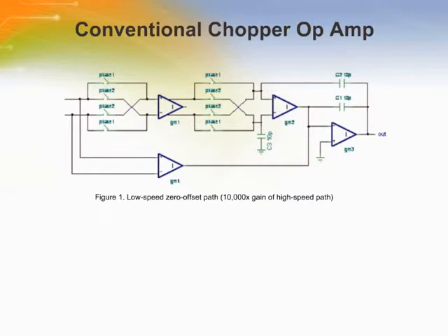More modern implementations of zero drift technology are quite common now in the analog industry. The essential element of a modern chopper amplifier is an input stage with synchronous commutation of the input and the output. The DC offset of the amplifier stage is effectively inverted on each half cycle, which results in the averaging of the offset voltage to zero.